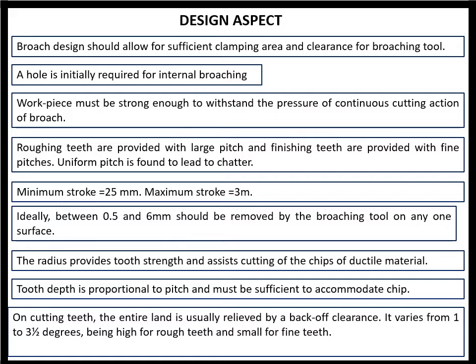The minimum stroke length should be 25 millimeter, and the maximum stroke that can be considered is around 3 meter. Removal of material by a single tooth is very important.